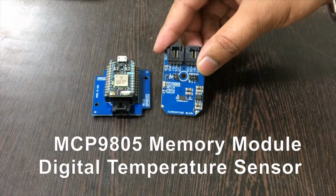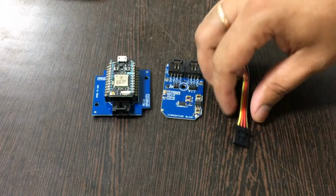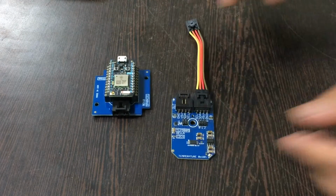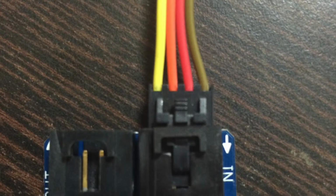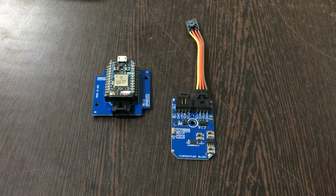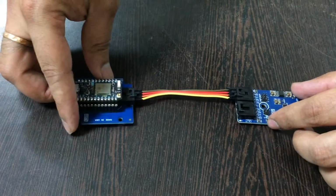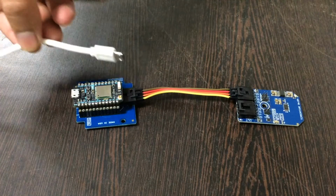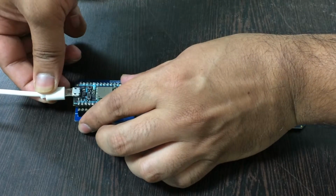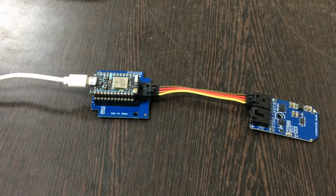Now we require our sensor, which is MCP9805, and a connecting cable. Make this connection like this. While making the connection of the sensor and the cable, please make sure that the brown wire of the cable should be connected to the ground terminal of the sensor and for the I2C shield also. Now, to power up our particle photon, we require a micro USB cable. Gently insert it over here and our connections are ready. Now let's have a look over the particle code.